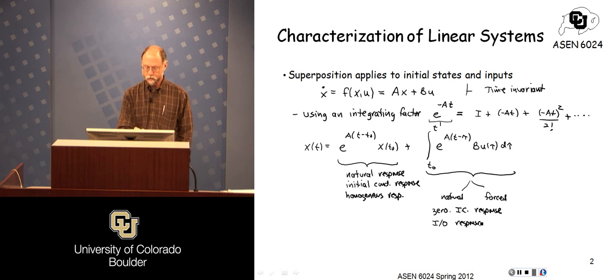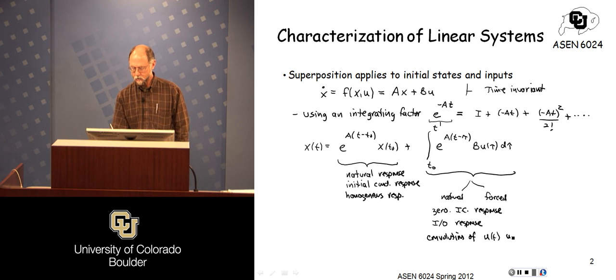In other words, with no initial conditions going on, the output is strictly a function of the input according to this convolution operator. So this is a convolution of the input u of t with the impulse response e to the a t.